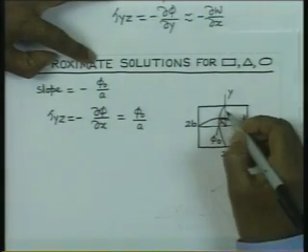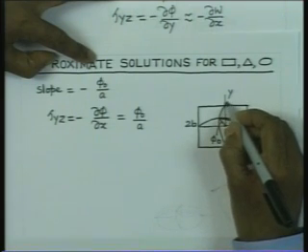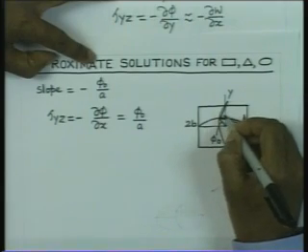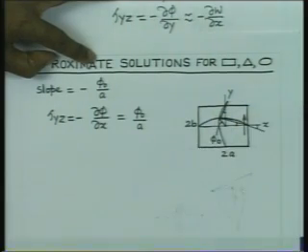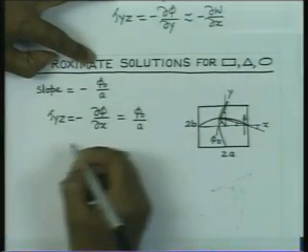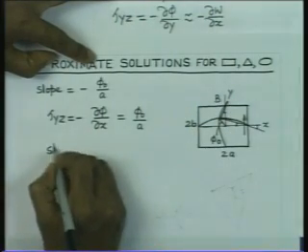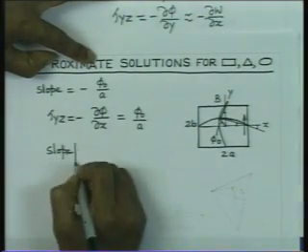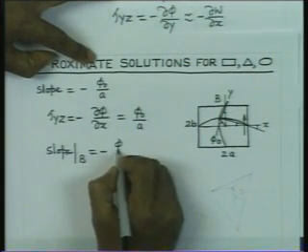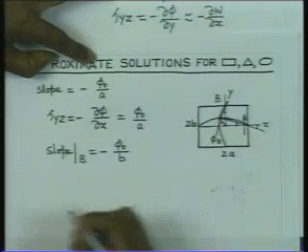Now, if you consider the curve here, the slope that we are going to get by joining the tip and this point, this is the slope. So, hence the slope at the end of the y axis, let us consider that this is point number B. So, slope at point B is equal to minus phi 0 by b, because this height is phi 0 and this distance is equal to b.